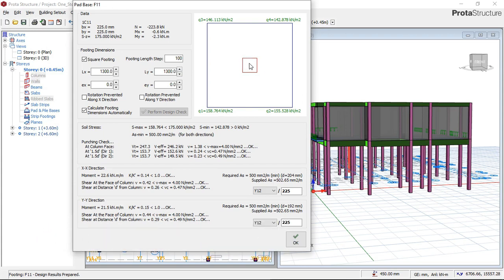As you can see the footing here, and the column here, the column is perfectly centralized. I would say that you should not put any value here, because once you put any value here, you are saying that the column is not at the middle of the footing. Let me just show you as an example. If I put a value here, let me say 200, this column will shift from the center of the footing, which is not okay.